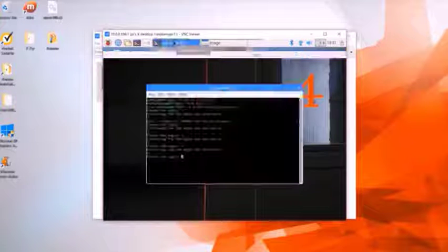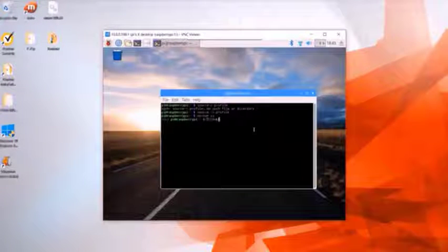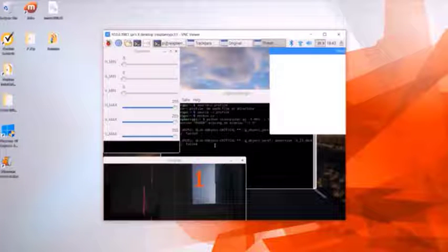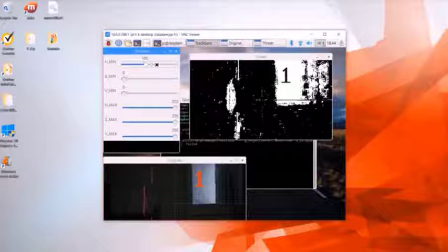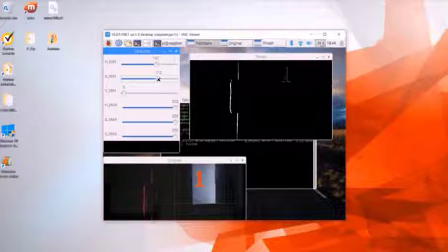This was before I began using an Ethernet cable, and my Pi's internet connection was not very reliable, resulting in disconnections while collecting data. In order to generate a 3D point cloud of my test target from the JPEG images, I first found the color mask values for the red laser line with the color picker code, which allows you to change the upper and lower bounds of the HSV color mask and displays the original image and mask results in real time.